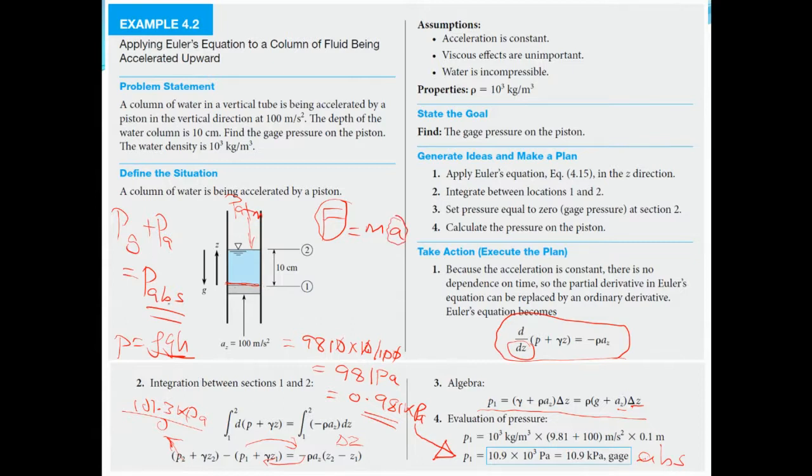So the pressure is increasing from about 1 kilopascal to 11 kilopascal because of the acceleration. This is very important, to understand exactly the application of Euler's equation. It helps us to determine pressure as a result of the dynamic nature of our system, that's when our system is in motion. In fluid statics, chapter 2, we dealt with, chapter 2 or 3?